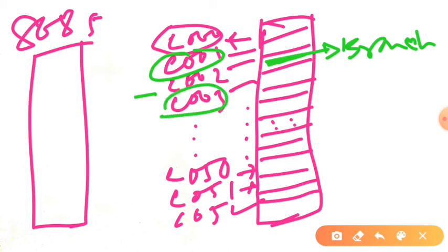It may change the way of program execution or instruction fetching. The program counter may be loaded with a different memory address, far from C003. It could be anything, so let us assume it is C050.